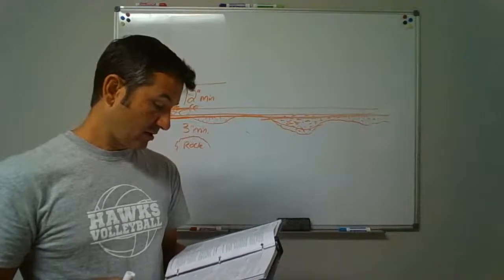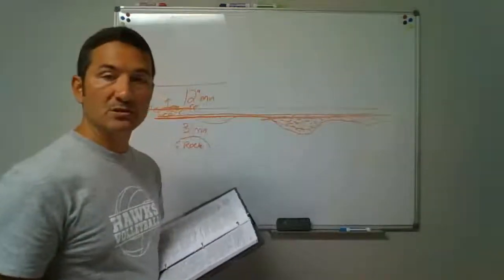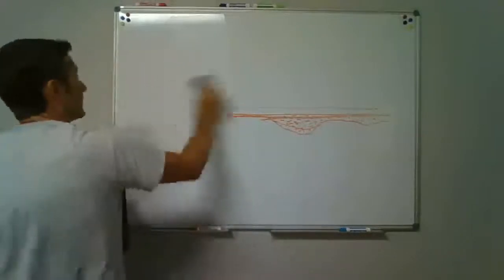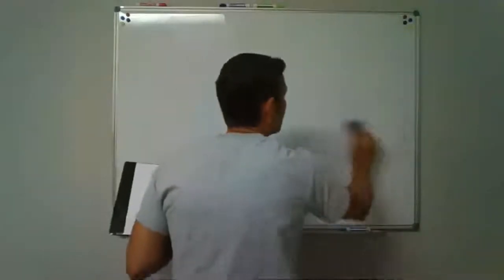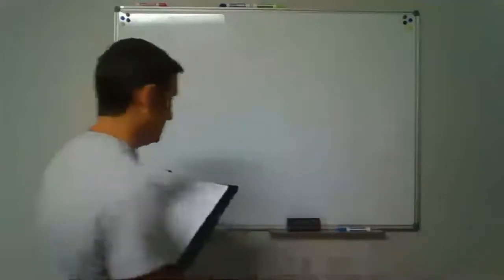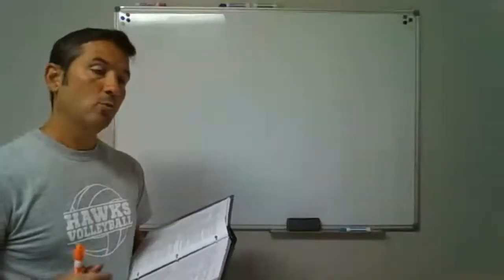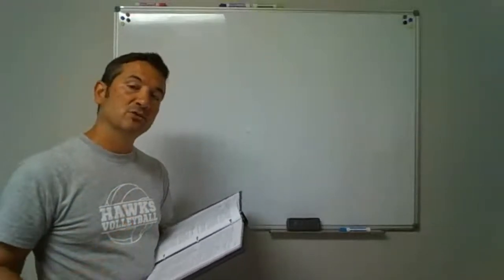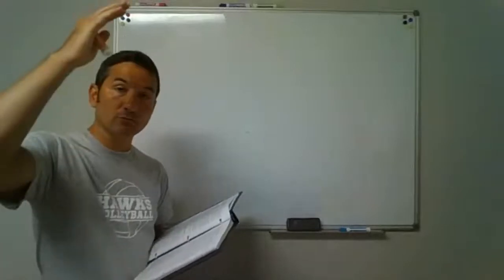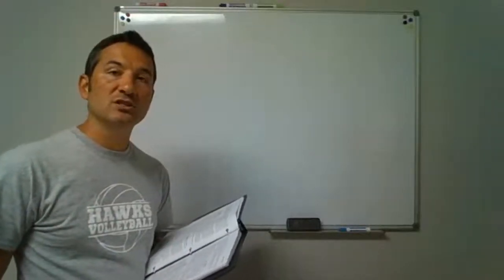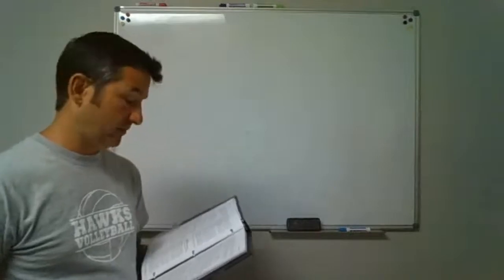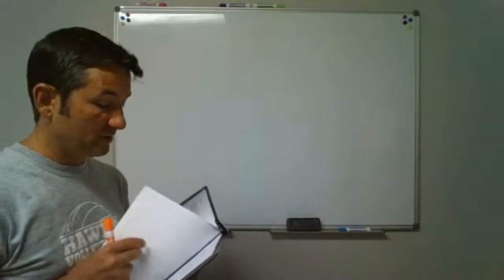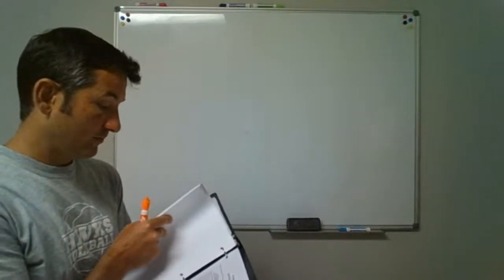Okay, but it says, all right, we don't want to just go in and start slapping holes wherever we want to place them. We got to be a little bit more careful in that. We don't want to compromise the structural integrity. That wood is there for a reason. It's either supporting the floor, supporting walls, supporting the roof, and if we go drilling too much and taking it out, we weaken the system. Okay, so refer over to Appendix C, and it will tell you what you can do.